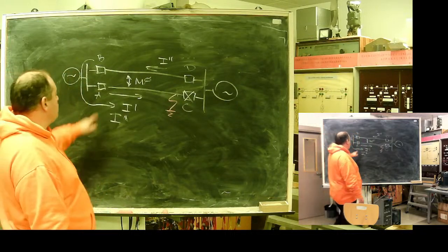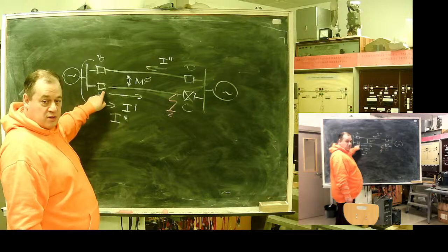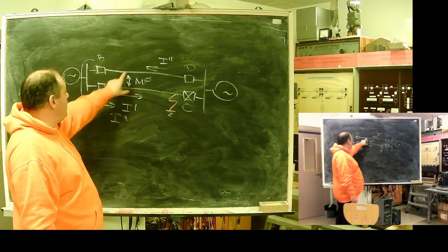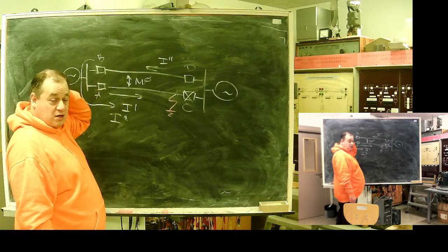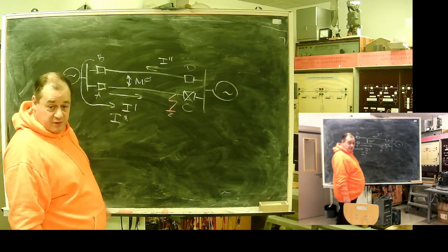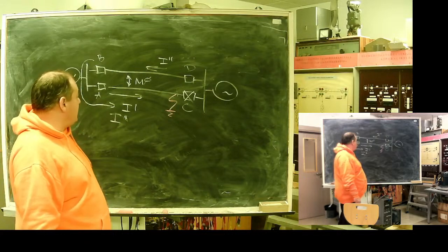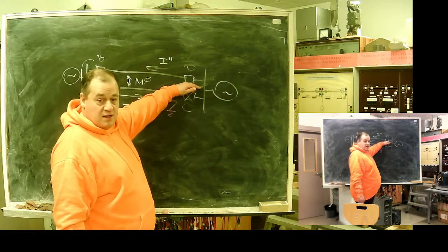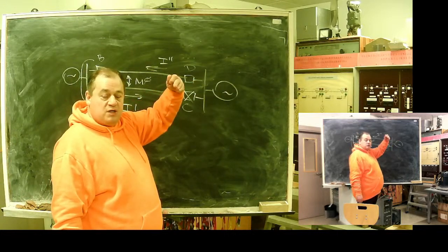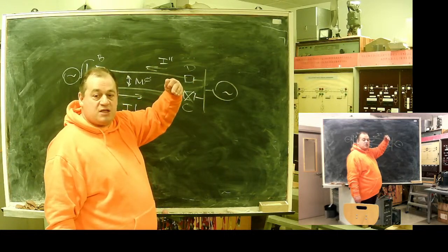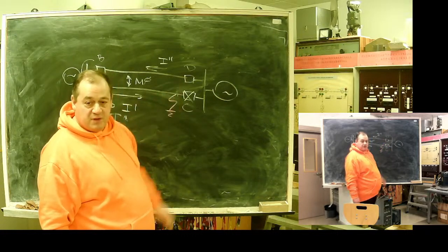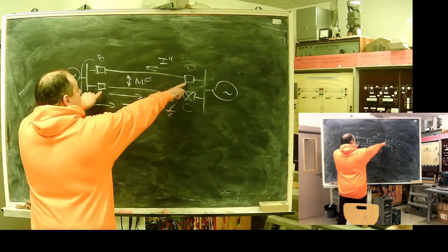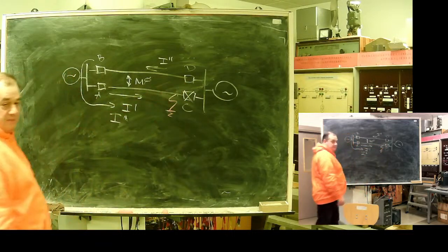Because for this one, decrease of observable resistance due to this mutual inductance causes speed up in operation. It's okay, this fault is internal. For this relay, fault may go into operation zone and cause false trip. Should be checked that the selectivity between them remains.